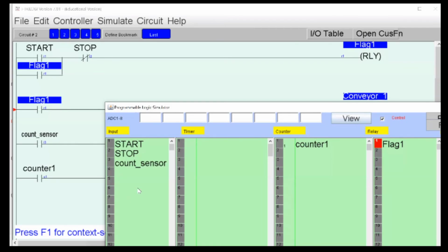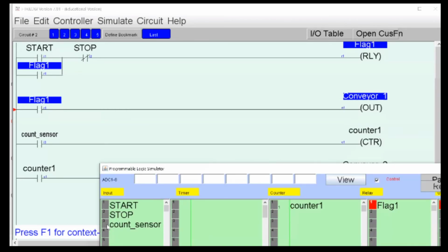It needs another drop of a plate. When the plate drops, you can see the number has reached the preset number 15, and the counter will be activated. The counter being activated means that all the contacts of the counter will change state.